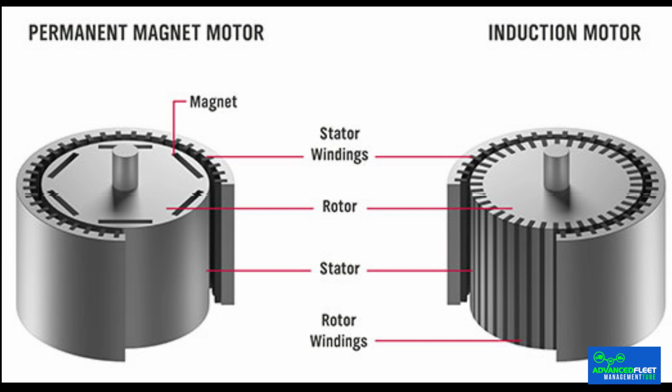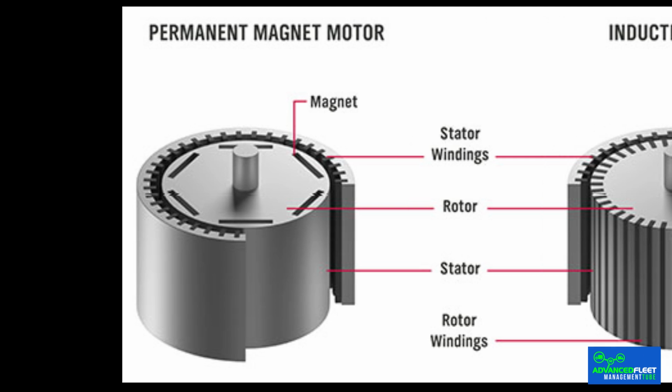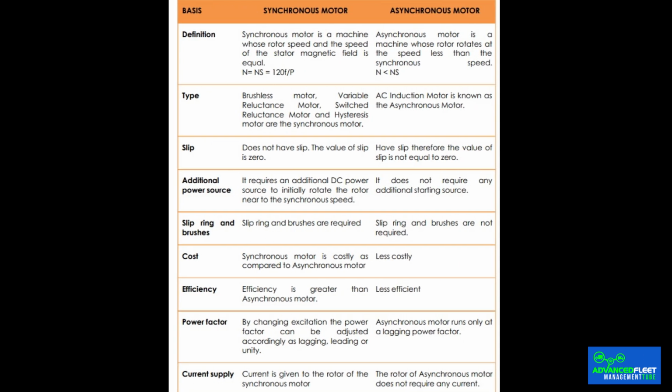Technological differences between synchronous and asynchronous motors. A synchronous electric motor generally incorporates permanent magnets composed of rare earth elements, such as dysprosium, gadolinium, or neodymium. These magnets provide magnetic flux when magnetized by another magnetic field and do not lose their properties once the source of the magnetism ceases. Embedded in the motor's rotor, they dispense with the use of an external excitation system and brushes, which are necessary to generate the corresponding magnetic field in the rotor and promote its rotation when exposed to the externally generated field in the stator.